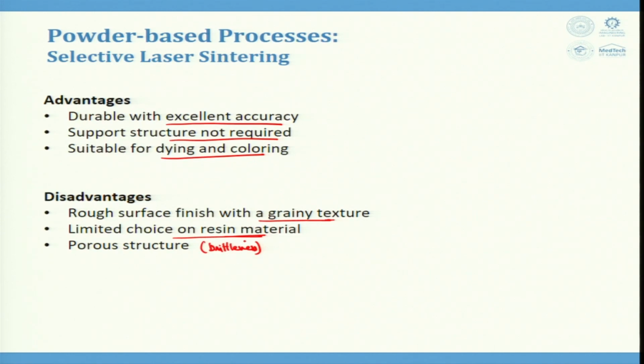And if I talk about the strength, finish and example materials here, the strength is between 5300 to 11300 psi, that is from 36.5 to 77.9 megapascal. And the layers that we have gotten here in the finish are of around 0.004 inches.